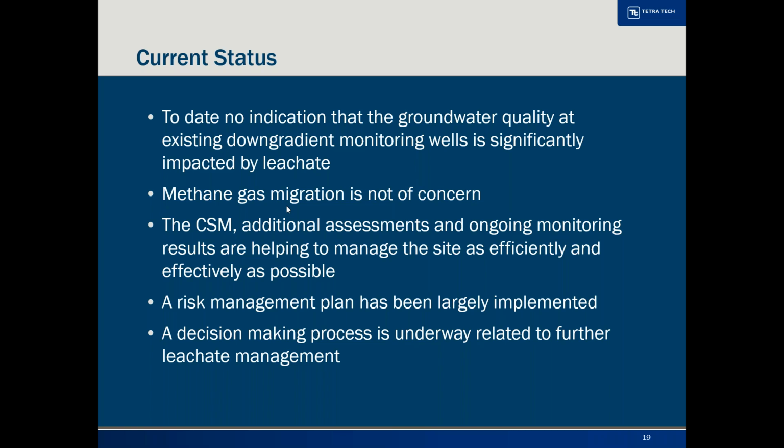First of all, the cost and the treatability of that leachate, but also if you pump too aggressively on the leachate, you might actually see adverse effects to the landfill by slumping waste, by cracking of the cap, and you might even also see more ingress of surrounding groundwater into the waste. So these things need to be evaluated, and the leachate recovery trial that was started 2 years ago will probably be continued to assess that further.